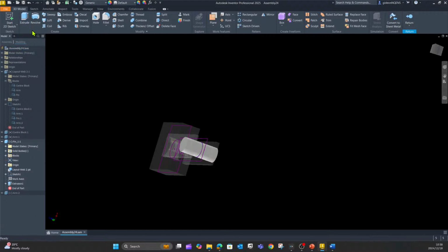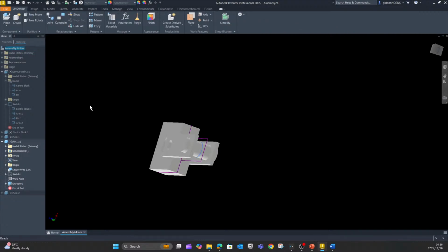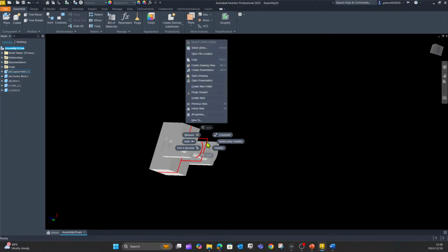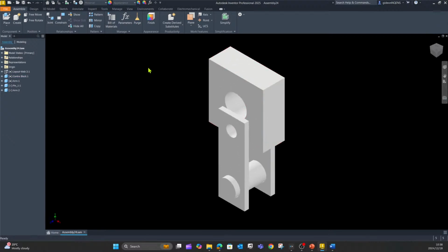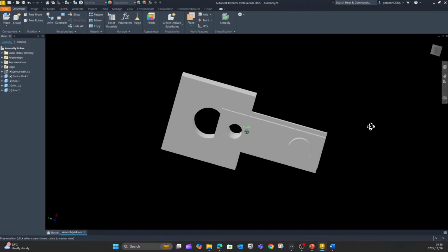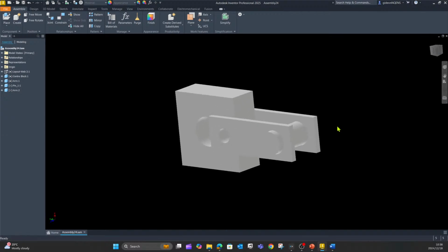I can go into the update, go into my main assembly, I can go into this sketch over here, I can right click on it and switch off the visibility of those sketches as needed or required. If I go to my home page, you'll see there I've got my assembly. Now you can go and create, for instance, another pin over here to get it through the block as needed or required. And you can go and make your changes.